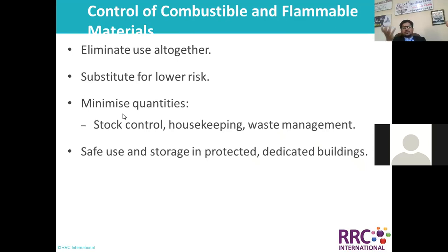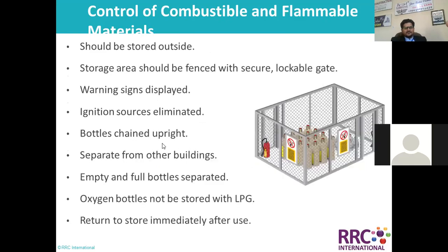More stock means more fuel, and in case of fire, more terrible consequences. Then there is safe use and storage in protected and dedicated buildings as well. Now, look at the pictures: combustible and flammable materials must be stored outside, away from your operational or production areas. The storage area should be fenced with a secure, lockable gate.